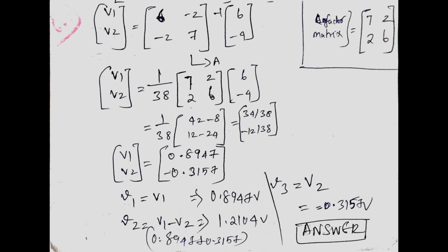In this way we form the matrix. Node 2 meeting elements are the 4 ampere source, 5 ohm and 2 ohm. That is important. In this way, node 1 is 4 plus 2, node 2 is 2 plus 5, the common element is minus 2, with capital V1, V2, and the sources 6 minus 4.